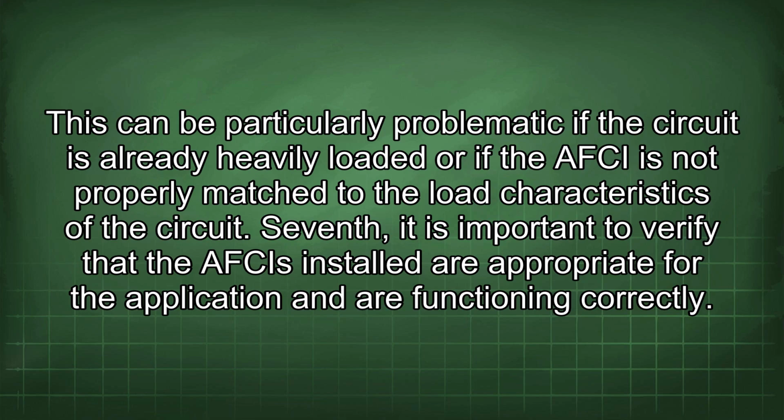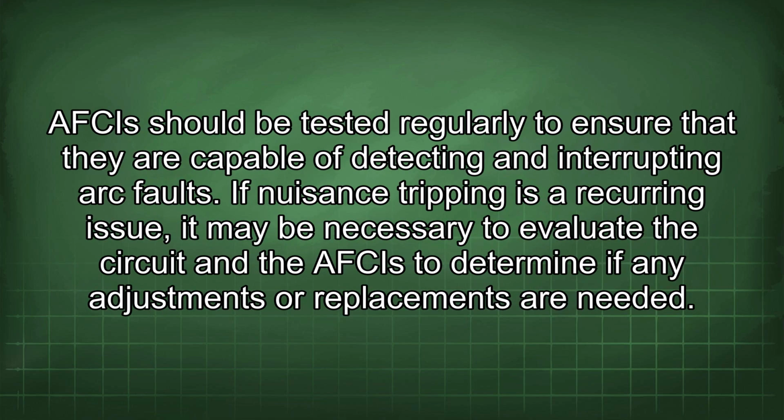Seventh, it is important to verify that the AFCIs installed are appropriate for the application and are functioning correctly. AFCIs should be tested regularly to ensure that they are capable of detecting and interrupting arc faults. If nuisance tripping is a recurring issue, it may be necessary to evaluate the circuit and the AFCIs to determine if any adjustments or replacements are needed.